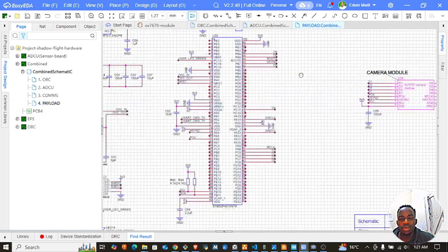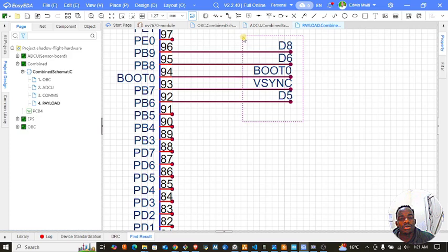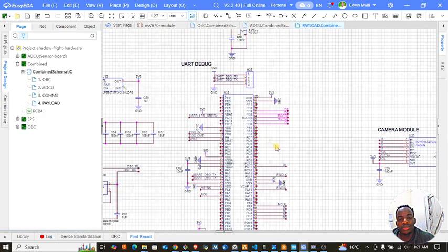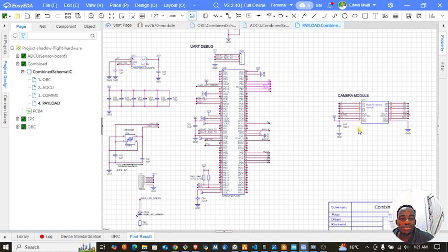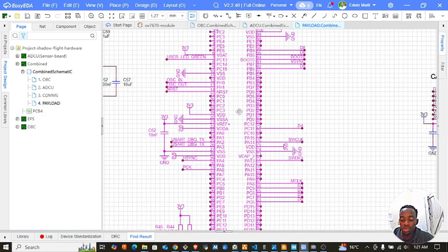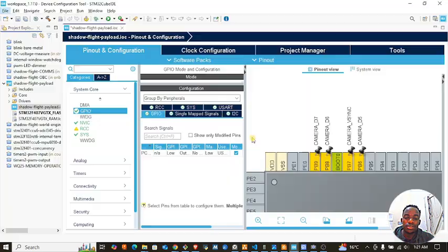the module to the DCMI pins of the STM32 MCU. So in part 3 we are going to do final additions like user buttons, and then add the connector interface, add the screw holes, design the footprint. So yeah, we have not done much in this video, but it's substantial to show how we route that camera to the STM32